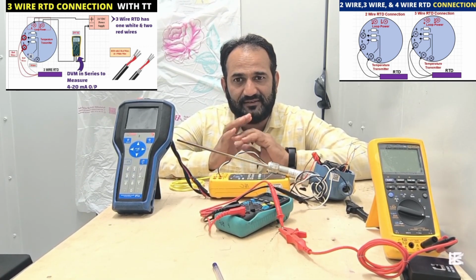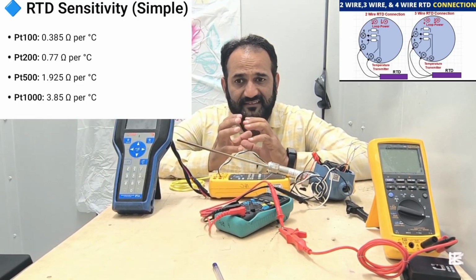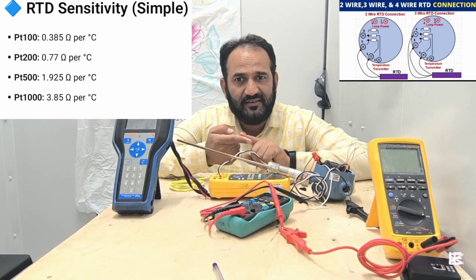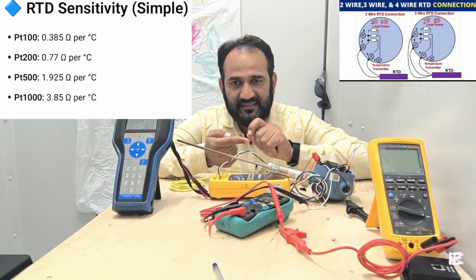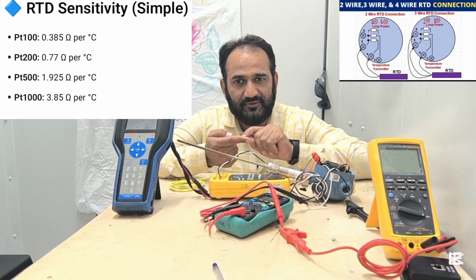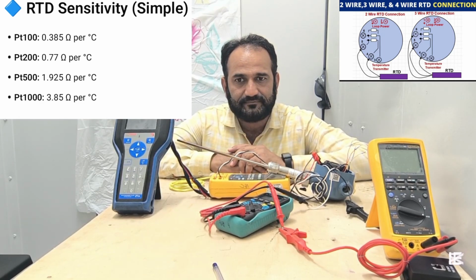The calculation is different for Pt100, Pt200, Pt500 and Pt1000. These all have different ranges and different sensitivity. For Pt100 the sensitivity is 0.385. So if we are getting 120 ohms, we subtract the 100 because we are using the Pt100, and we divide the 20 by 0.385 ohms and we get the degrees Celsius.